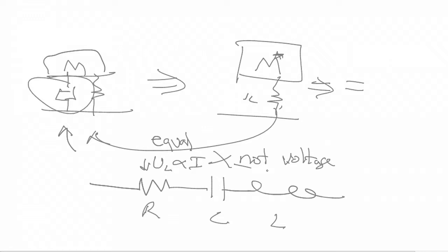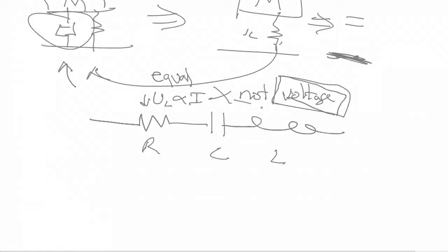We know that in actual systems, meaning in actual materials, not necessarily devices, a resistor's loss is proportional to the current squared, that is, the power. For materials like capacitors, their loss is proportional to the stored energy. Therefore, if you're modeling some type of resonant system with a capacitor, it would be more appropriate to use a complex value for the capacitance.